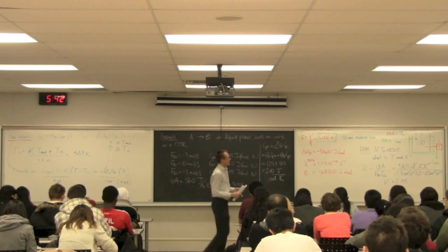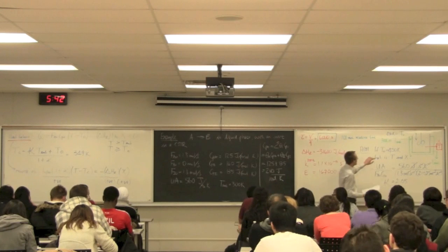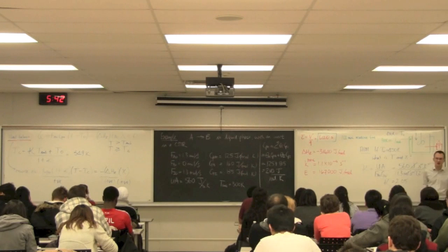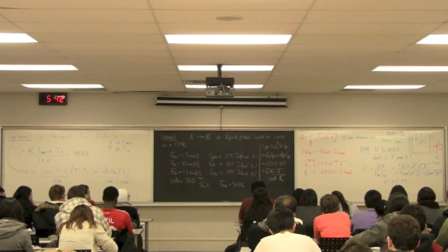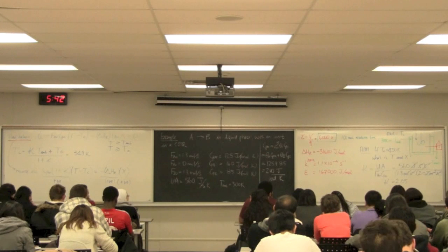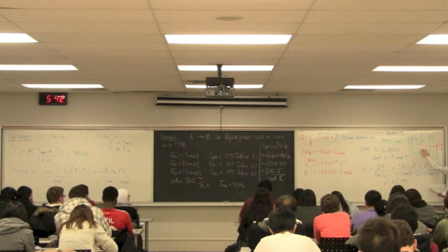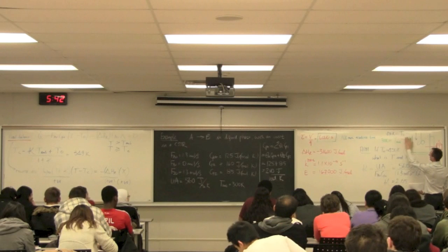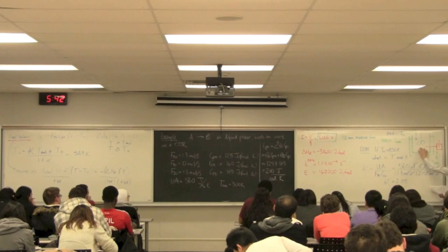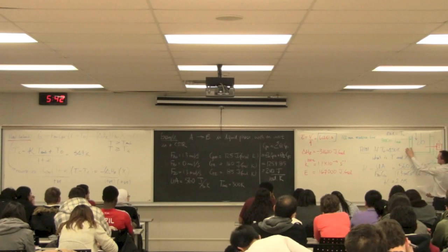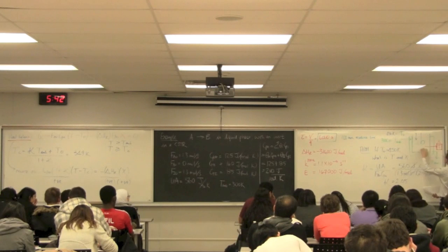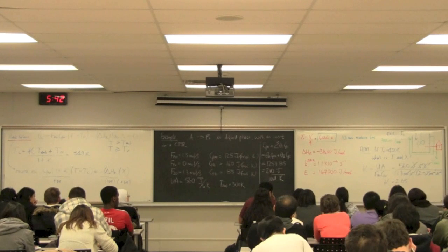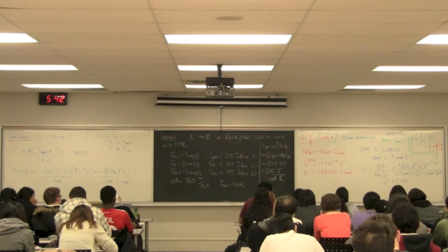So there isn't really an upper bound. Just by looking at what we've got here on the board right now, we don't have an upper bound. We know that there's an exothermic reaction taking place. If I have a material entering at 450 Kelvin with an exothermic reaction occurring, and this heating medium is not removing heat fast enough, it's quite likely that the temperature leaving can exceed 450.